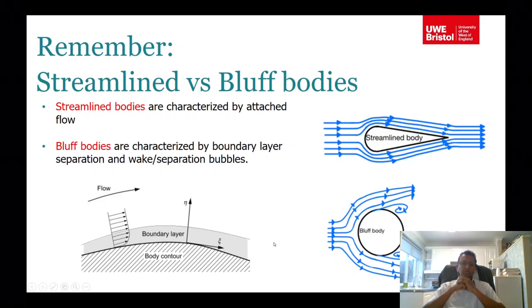something forms over that, which is called the boundary layer. What this means is that the velocity just above the surface is 0, and around here, this line is normally drawn at 99% of the free stream velocity. That is called the boundary layer. This notation is important for you to understand the boundary layer effect and the forces acting upon a car.